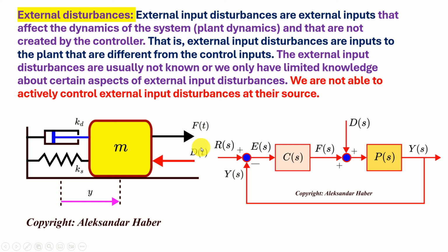And over here, we have the disturbance force. This disturbance has a unit of force, and this is the action of the environment on our mass spring damper system. For example, someone can hit the mass with a hammer, or there's some external vibration affecting the mass motion, or maybe this whole system is sitting on some vehicle and the vehicle accelerates and decelerates, and then the acceleration can be modeled as inertial forces, for example, or a similar type of modeling.